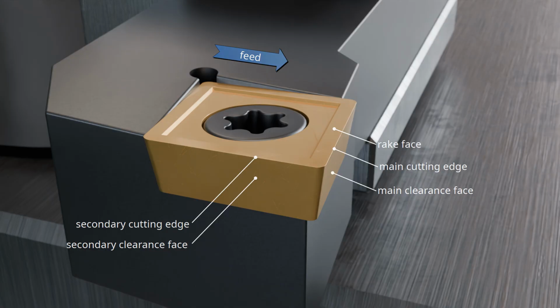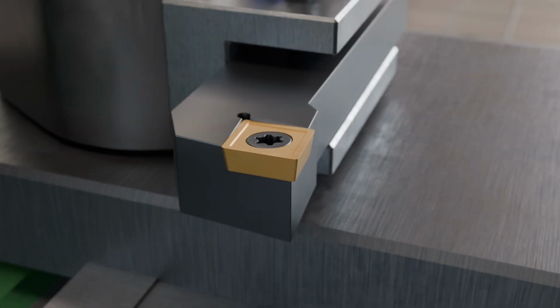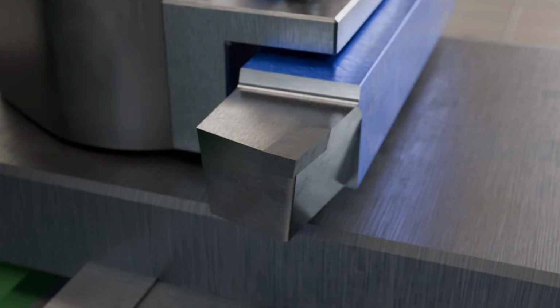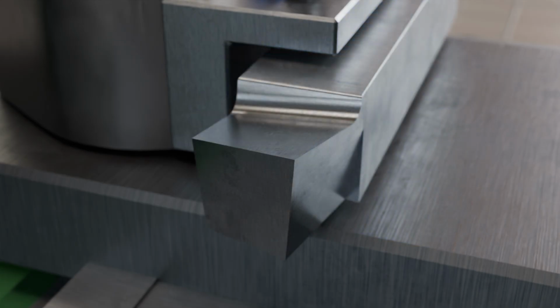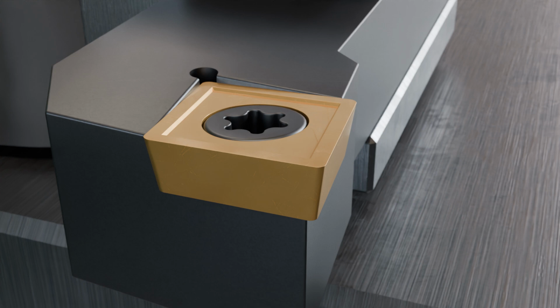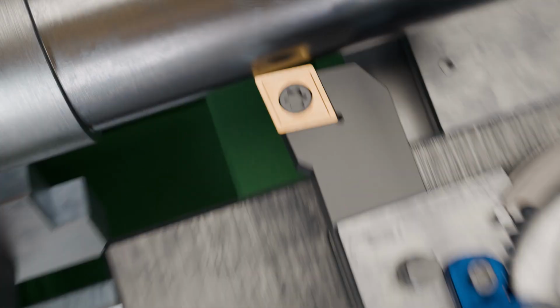In addition to turning tools with carbide indexable inserts, there are also turning tools with brazed carbide tips. In rare cases, turning tools made of high-speed steel are still encountered. However, indexable inserts have the decisive advantage that a wide variety of consistently reproducible cutting geometries can be selected, allowing optimal adaptation to the given requirements. Furthermore, screwed or clamped indexable inserts can be quickly replaced when worn. Compared to cutting edges made of high-speed steel, carbide indexable inserts allow significantly higher cutting speeds.